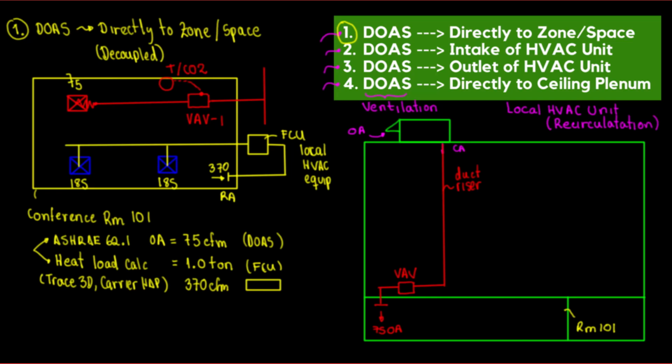Now in the same schematic, I'm gonna show my other unit. The other unit is yellow, I'm keeping consistent with what it is in there. This unit is gonna be located outside. This is the ceiling plenum, and this is the FCU. Then I'm gonna make my main duct in here, and from the main duct I'm gonna tap down.